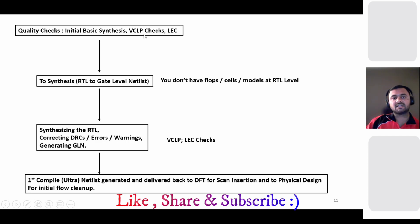Then we do some low power checks. If your UPF is there, we check that all the power crossing boundaries are correct between one block and another, or inside if there are multiple power domains, so the DRC should be fixed. Then you check the logic equivalence, before inserting the DFT logic and after inserting the DFT logic, the functionality should not change. So that's what we do here in the quality checks. And then we deliver it to the synthesis team.